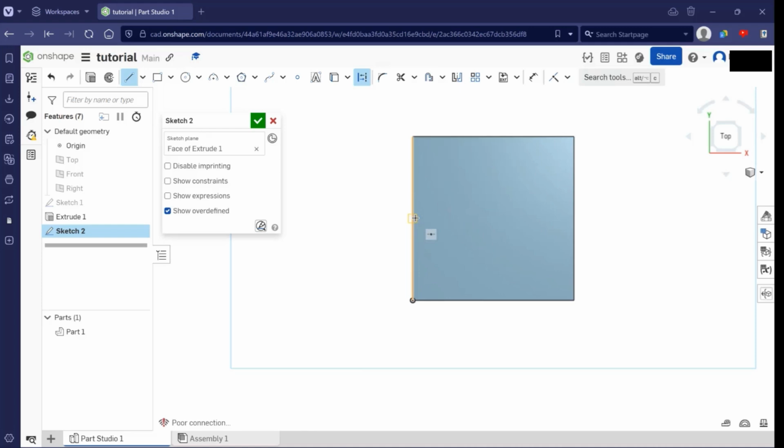That is known as a relation. So this relation, the line and then the dot, that means the midpoint. So this is exactly what we want. And this one with the two lines intersecting, that's called coincidence, which means they're touching each other. Okay, so what we want is coincident and also midpoint. So here.